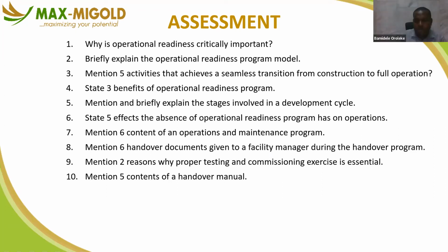Thank you, sir. But quickly, sir, the snag list, is it the responsibility of an FM to do the snag lists? No. To check through maybe during testing and commissioning? During that period, the snag list is produced by the construction team. But the FM who is going to take over is the one pointing out things for them to put on that snag list, and is the one going to monitor the tracking of rectification of those snags. It's like your first FM task on the project.